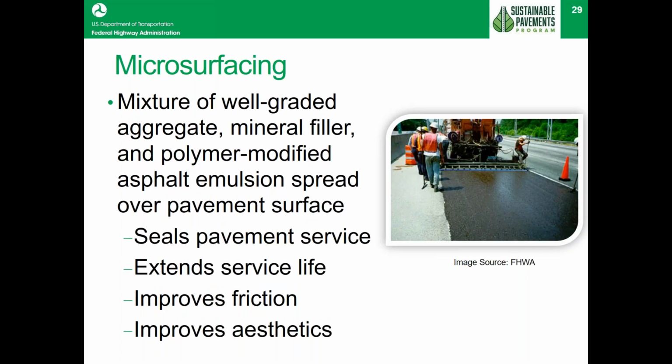The next surfacing we'll talk about a little bit is microsurfacing, and this is a little bit similar to a slurry seal, but it is done usually with more select materials and very, very careful placement when it goes down. It is a lot more costly because of those select materials, but a surface like this can last as much as 10 years or even more in some locations. Sometimes they use these microsurfacing projects to correct rutting problems, and it can be used on roadways where there are some high traffic levels as well.